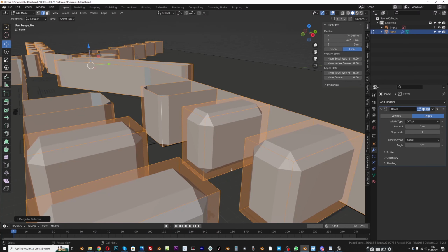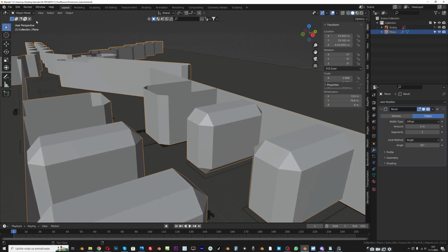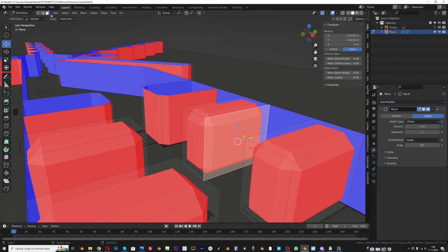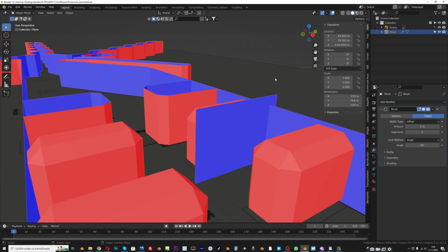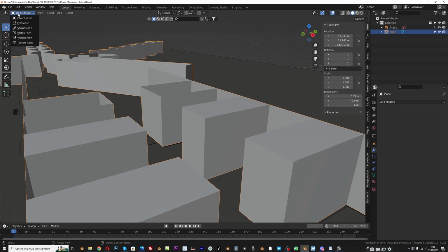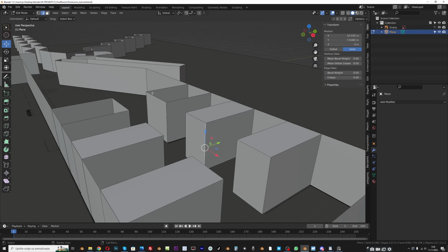And another common problem here, if you for example have two faces facing in another direction, for example if you go here to face orientation, you can see that we have blue color here and red color here. But if we flip this normal orientation, you get... I will just for now turn off this bevel modifier, and if I go here with Ctrl B, you get this problem. You always need to have blue colors where the camera is.